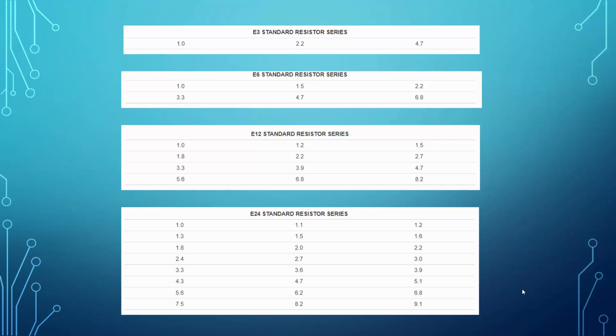Since some values in the E24 series do not exist in the E48, E96, and E192 series, resistor manufacturers have added the missing E24 values to some of their 1%, 0.5%, 0.25%, and 0.1% tolerance families. This allows easier purchasing migration between different tolerance parts. There is also a table for E48, E96, and E192 series that you can find on the internet.